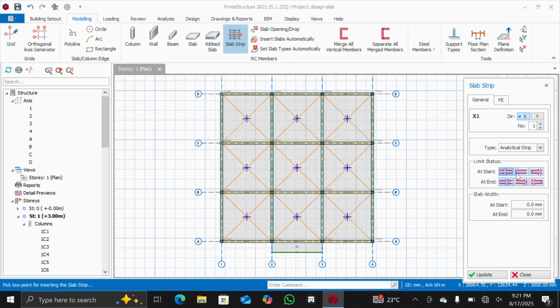When I come to these two here, this one in the middle, that's for when the slab is beginning at the edge of a discontinuous beam. It normally occurs at the perimeter beams, like these ones. These are perimeter beams. So that one is when we are pulling it from this side up to this side, from this end to this end. That's the one in the middle.